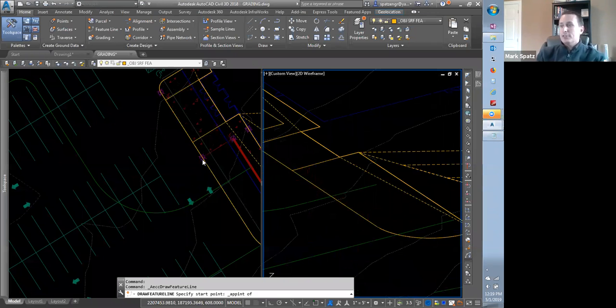And if I do that over here, it may get the feature line, or it may get that line down at 0 below it. Whereas if I come over to the 3D view, it's only going to get the feature line. See how it's the X with the dot, dot, dot? So I'm going to pick anywhere along this feature line.